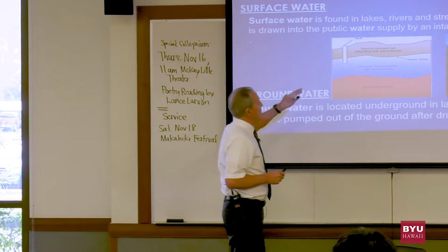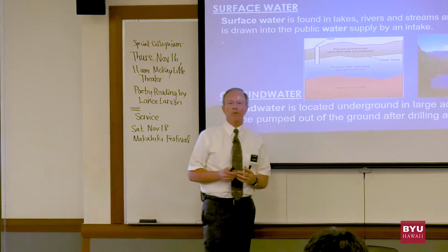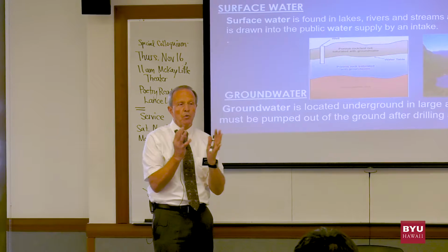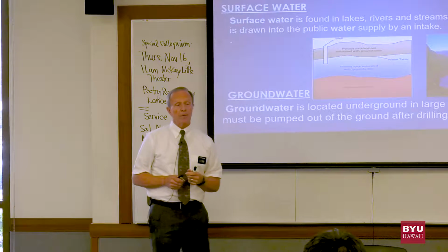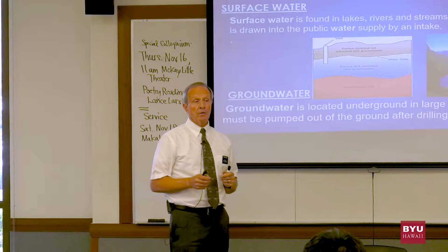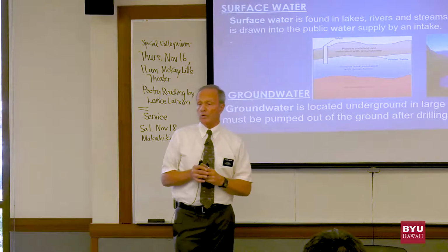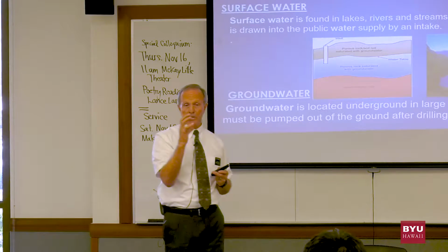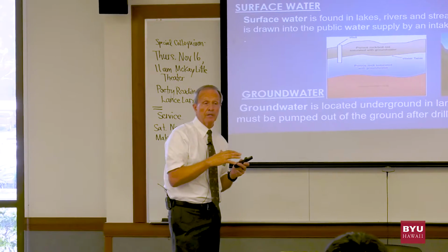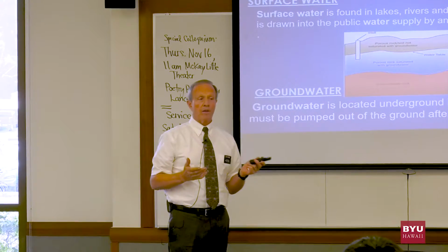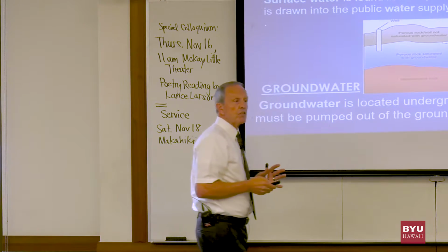You have a top layer, then your actual aquifer, and then maybe a bedrock or something, what they would call a confining layer. A confining layer keeps the water in a certain place. If it's not confining, that water is going to move wherever it wants to. It doesn't move very rapidly. It can take hundreds of years to move a few miles. But this water is stored in the earth in an aquifer, and it moves based on the porosity. What's the porosity? The porosity is how big the openings of the fractures are that the water is stored in. If you have large openings, the water is going to be able to move rapidly, comparatively speaking. If it's real fine, or if you have clays, that's a confining layer. It cannot move through that formation, or it moves very slowly. So these are the things you have to be aware of as you start.